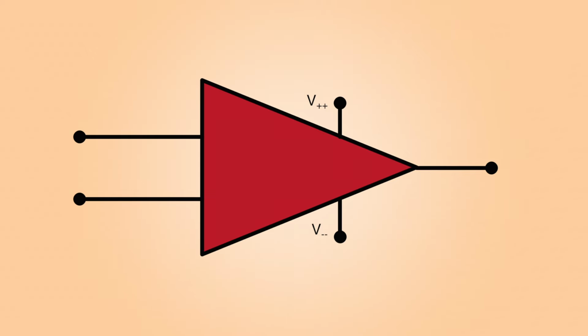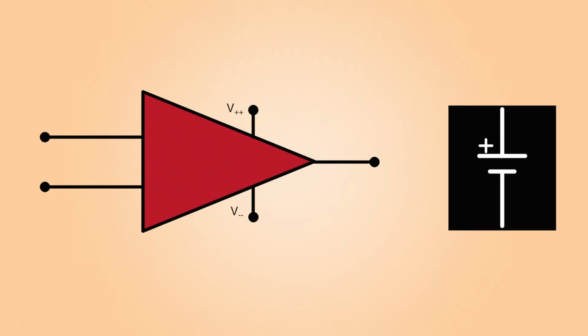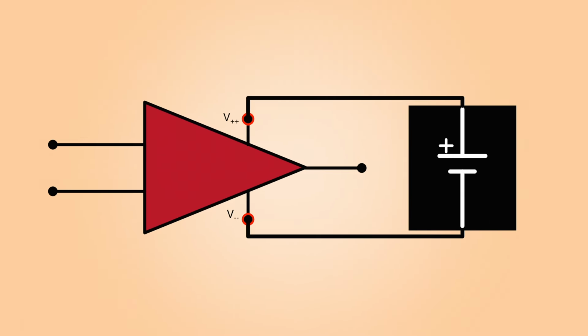Now, the first thing to understand about op-amps is that they are an active device. So unlike resistors and capacitors, which you might have worked with before, those are passive devices. There's no power supply or anything that's necessary in order for them to be able to do what they do. An op-amp, on the other hand, you do need a power supply. There's going to be connections to the power supply, and we'll include those in our model later on, but for the time being, we're not going to show those. We'll get to that level of detail later. So for the moment, we're just going to concentrate on the input and output terminals for our op-amp.